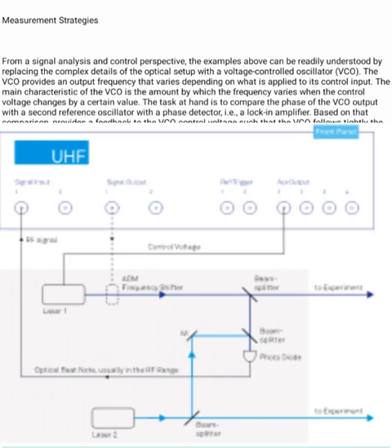Supportive user interface. Setting up the parameters that lead to stable operation is a key step. Phase unwrap over plus or minus 1024 pi enables robust operation. Depending on the amount of phase noise, you will need a high servo bandwidth. The UHFLI lock-in amplifier guarantees a servo bandwidth of up to 100 kHz. The PID Advisor comes with a VCO model that allows you to model the laser setup and calculate sensible starting parameters. Once locking is achieved, you can optimize further the PID parameters with the auto-tune routine to minimize the residual